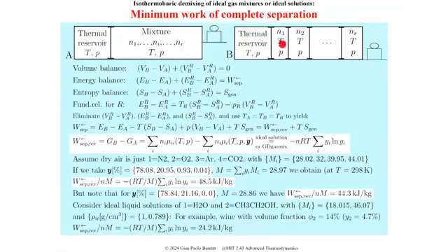So I do a volume balance for the overall system, including the reservoir. Here I call B and A: B is the final state, and A is the initial state. So the energy balance, the entropy balance, and then the equation for the stable equilibria of this reservoir with variable volume, which is this. Then I combine, as usual, these equations by eliminating the reservoir variables. And here I'm also using the fact that, since we are in equilibrium with the reservoir, it fixes also the final temperatures of the pure components at the end. So TB, TA is equal to TR.